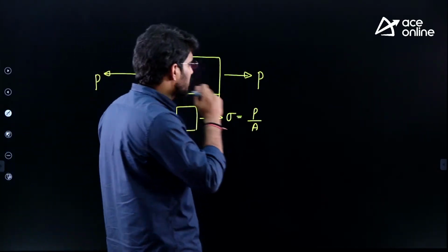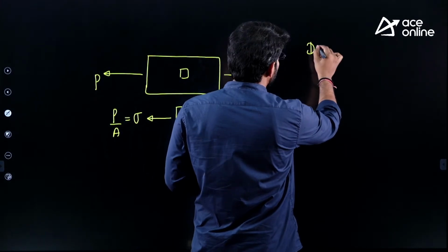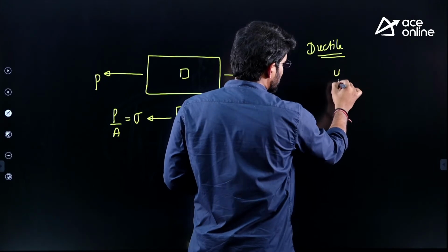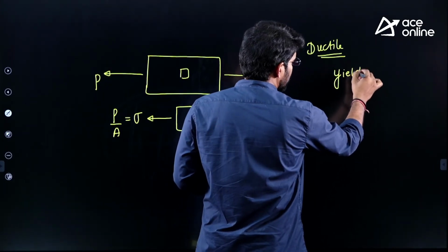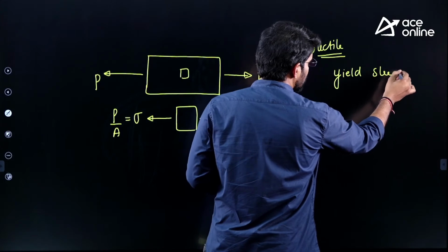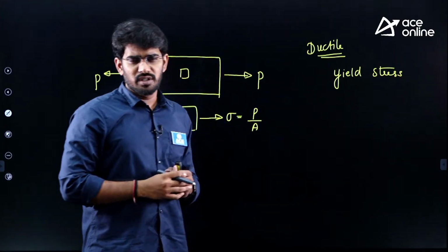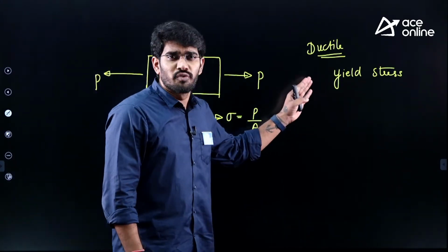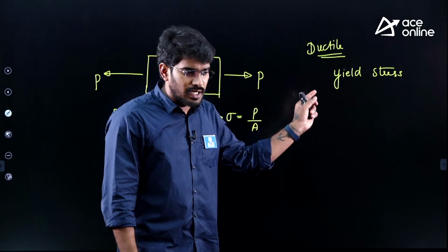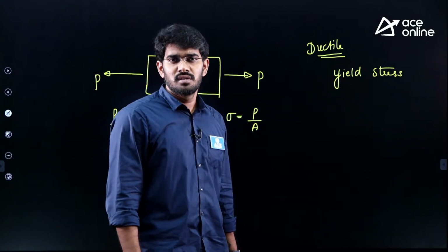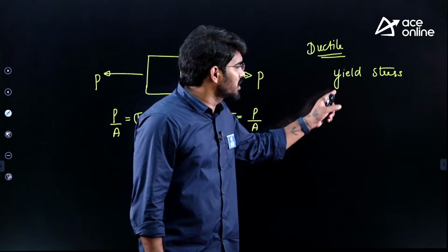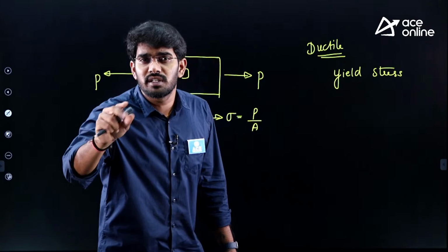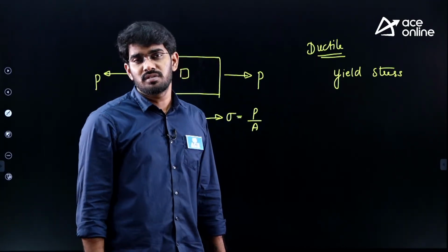In case of ductile materials, from experiments, yield stress is identified. Yield stress, whether in tension, compression or shear, is identified. For a given material, we know at what value of stress it is entering into plastic region, which means if the particle is loaded beyond this value of stress, it will enter into the permanently damaging region.